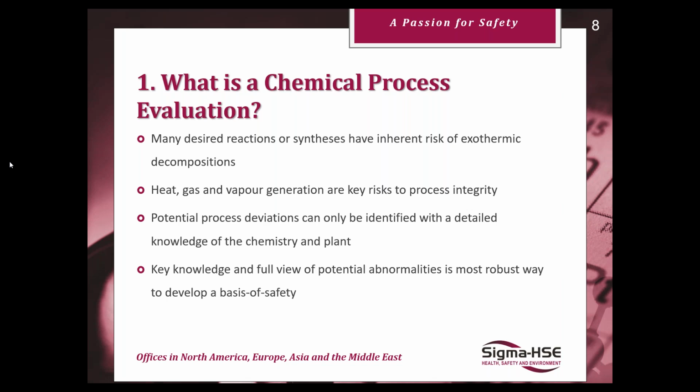So this really requires a detailed knowledge of, A, the chemistry you're actually going to be performing, and B, the configuration of your plant, the servicing, all the valves and pipes and things like that that may have an impact on how your process could go wrong should the worst happen.